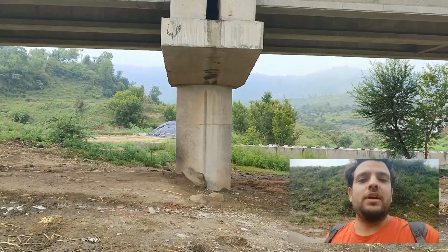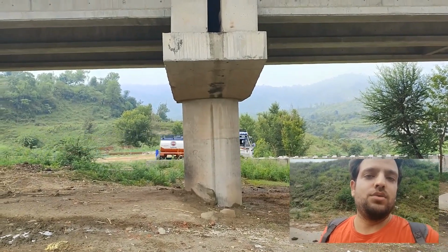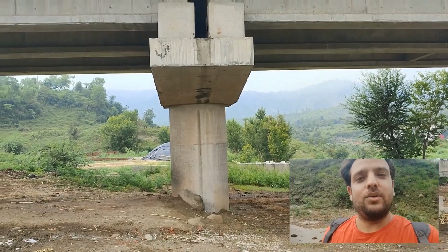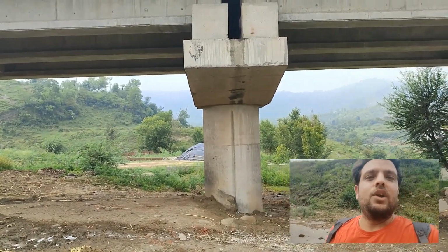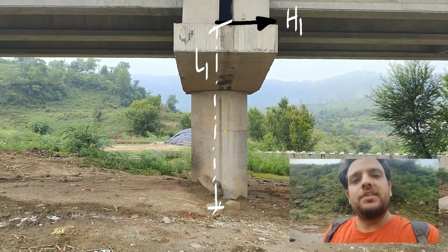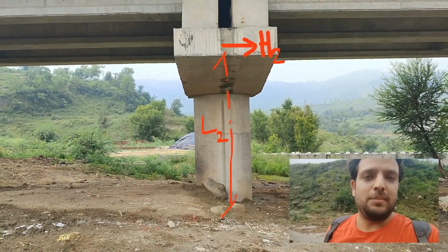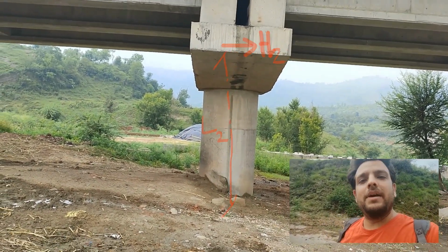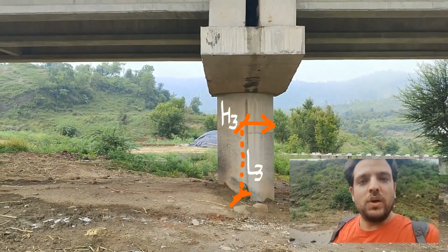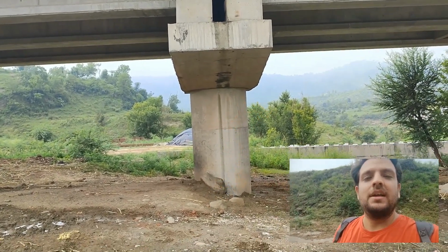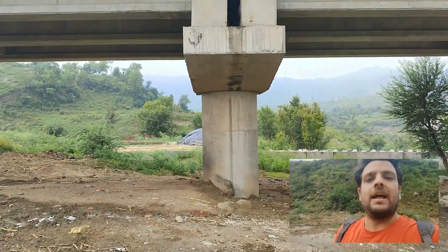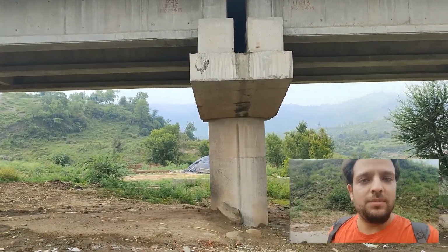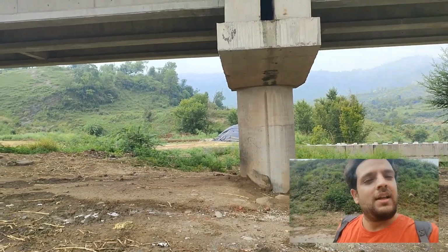First of all, the main horizontal force is due to the braking forces acting on the pier, acting on the superstructure due to the live load movement. Secondly, longitudinal seismic forces, which are calculated by the seismic coefficient method by multiplying the base acceleration AH with the seismic weight of the superstructure, the seismic weight of the pier cap, and the seismic weight of the substructure as well, and that is acting at their respective lever arms. That also induces a longitudinal moment.